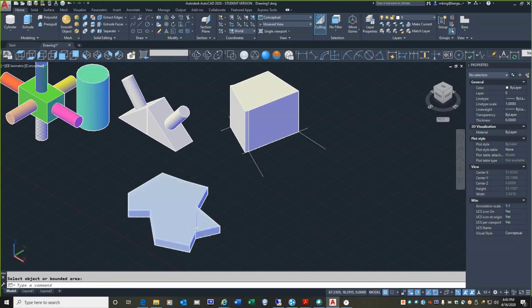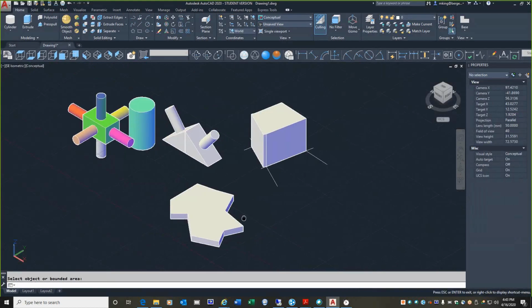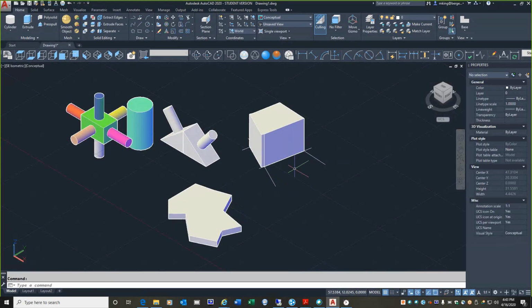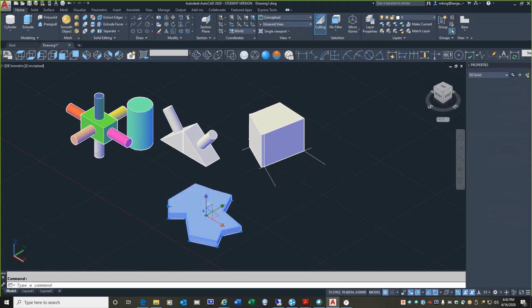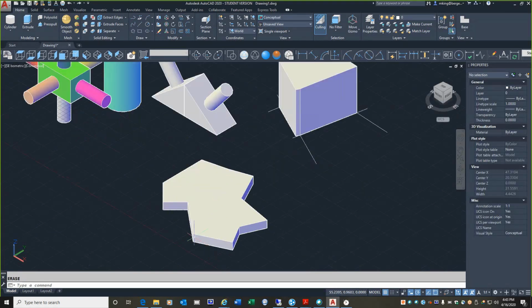All right, so let's zoom into this last shape we've just created. And just, by the way, just so you know, when you do what we did, where you draw 2D lines and create the shape with press pull, it does not erase the shape. For example, if I click and erase or delete this, my original boundary remains. So sometimes that can become an issue, and I'm going to show you when that can become an issue in a minute. All right, so zoom back into this thing,